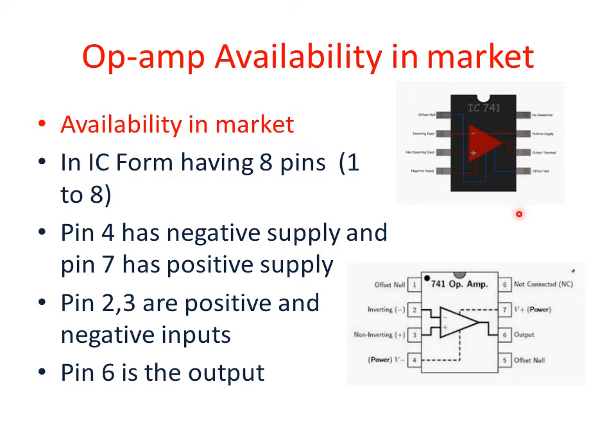However, whenever you purchase any IC from the market, you can see its data sheet from the internet. On every IC, the serial number is written on the IC. Whenever you put that serial number on Google, the detailed sheet of that IC gets opened and you can see its diagram inside and the pin number details.